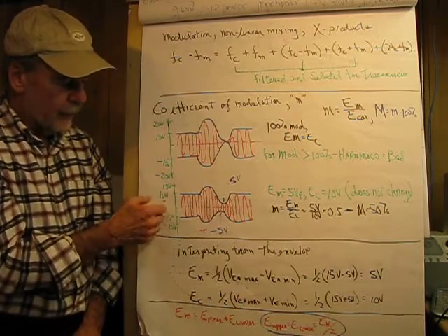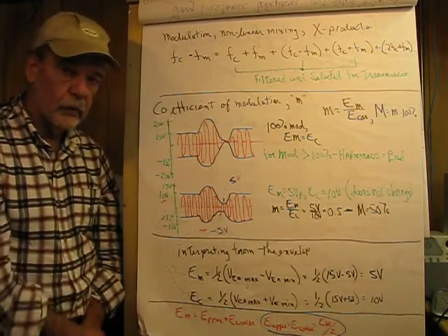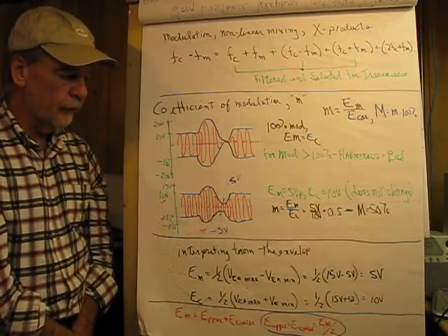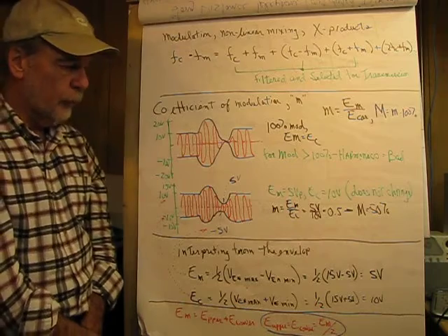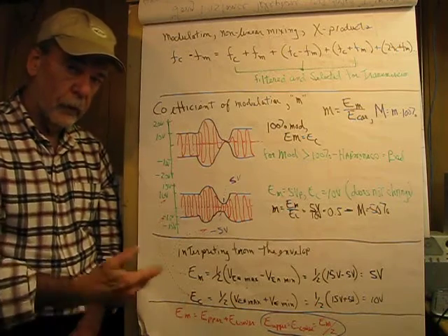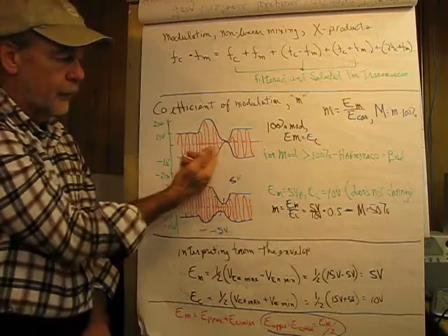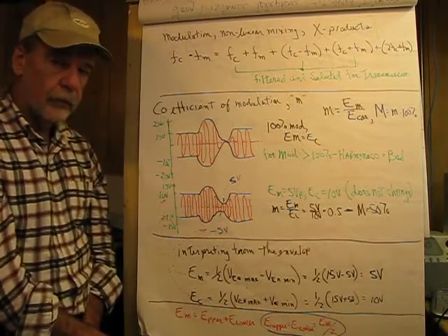So if we have 0% modulation, we just have the carrier, no sound comes out of the radio, and as we increase the modulation percentage, it gets louder and louder. Now some people may ask, why do commercials seem louder than program material? And the answer is that, seeing that the range is 0 to 100%, what they do with speech is they compress it.